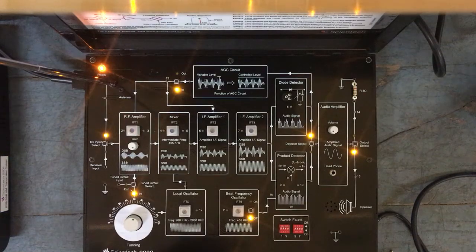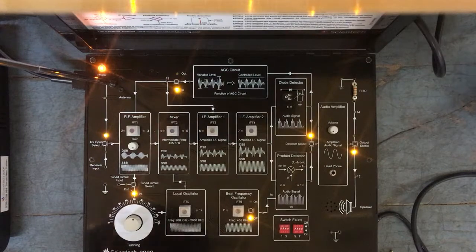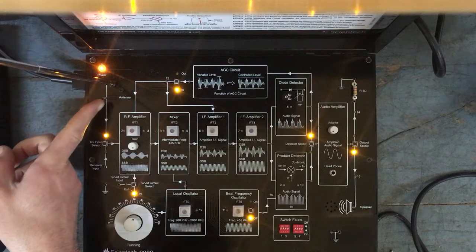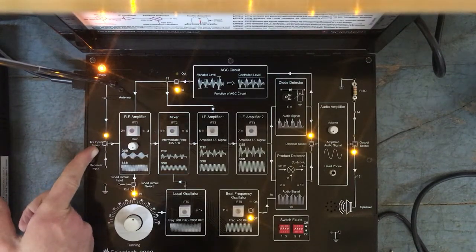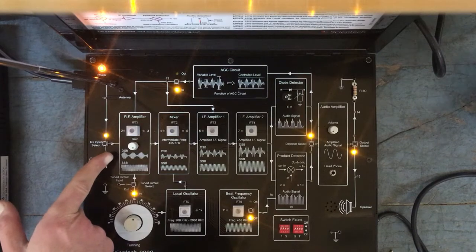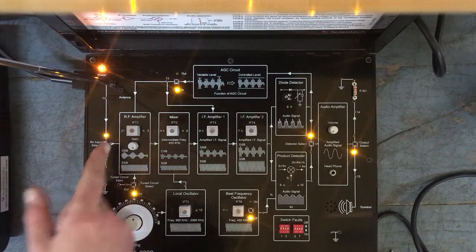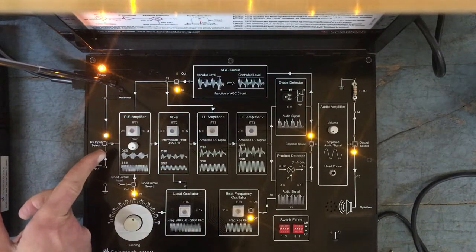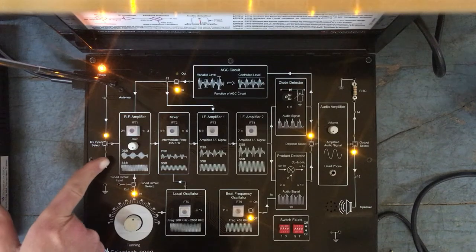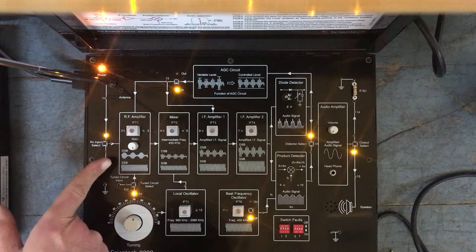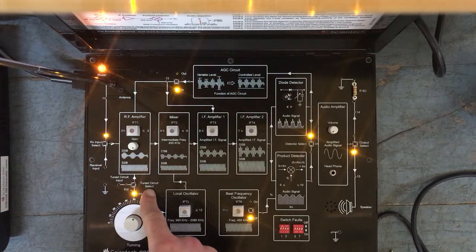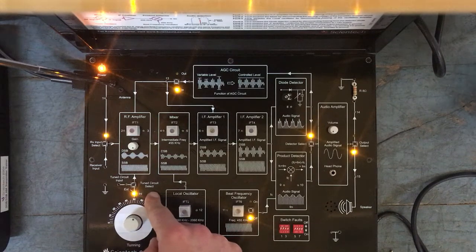Okay, on the receiving section, on the receiver, the receiving antenna actually receives a signal, and that is fed first to the RF amplifier stage, whose gain we have put to the maximum. That would be centered at our carrier frequency, which is 1 megahertz in this case, and it needs to be tuned, because we can change the tuning frequency